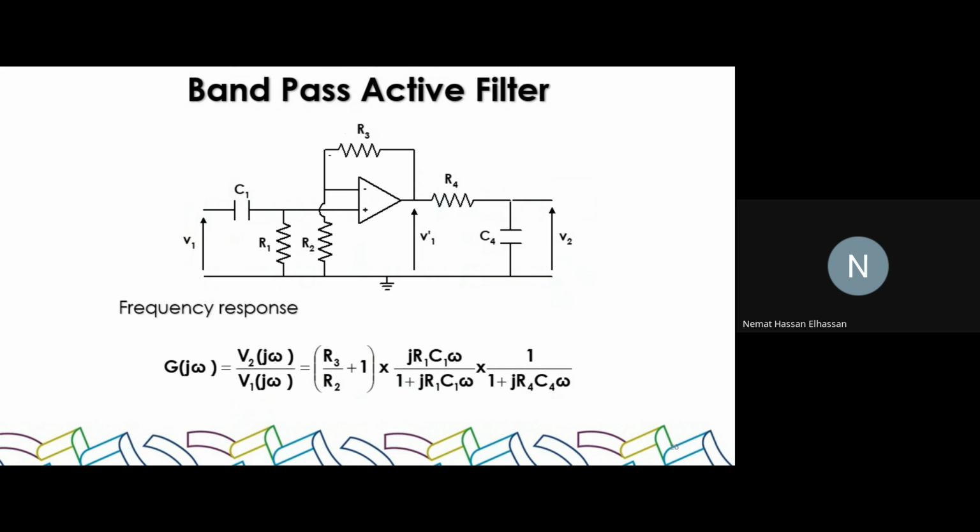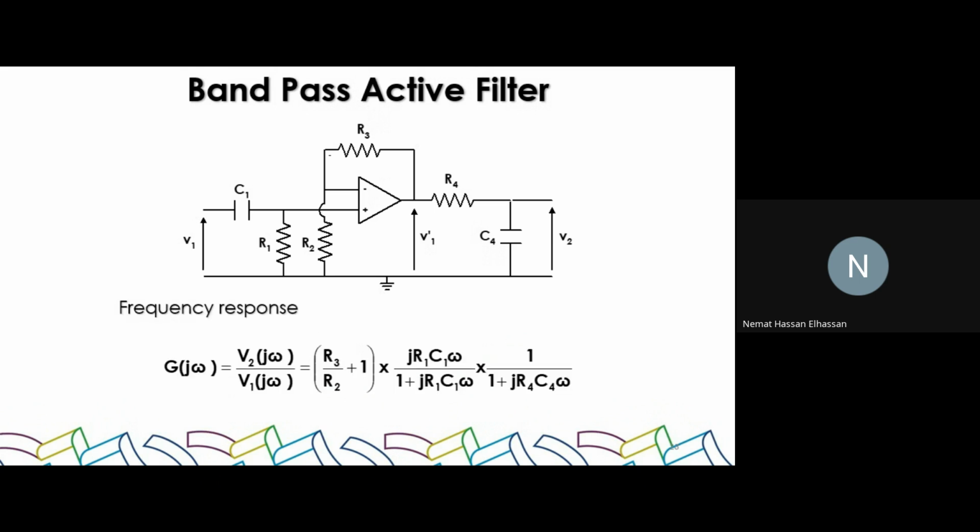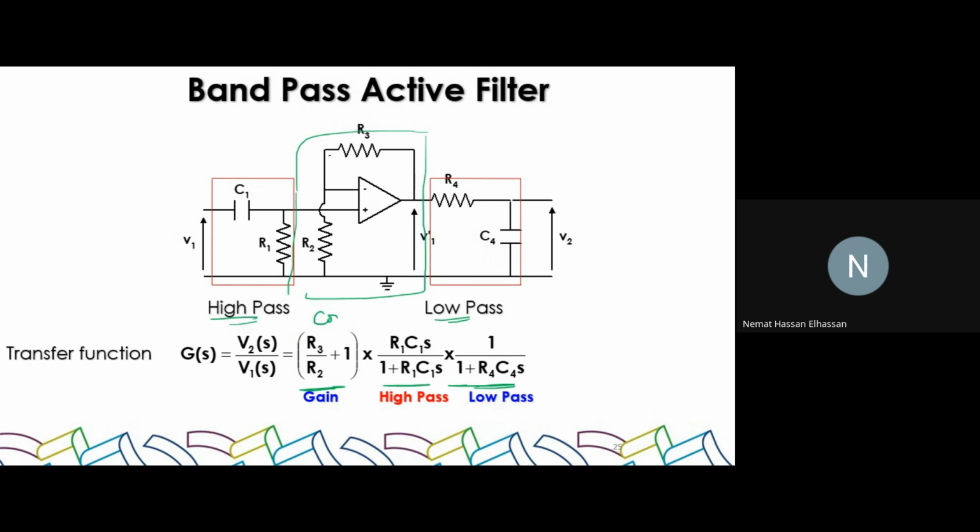So this is how you build a band pass active filter. And it will look like this. It will be the exact same frequency response of a band pass. The only difference is that the maximum gain value, instead of 1 or 0 decibels, will be 20 log the gain of the op-amp. Because if you look here, the transfer function has, well, let's go with the S1. It has a constant, it has a 0, it has 2 poles. Make sense?